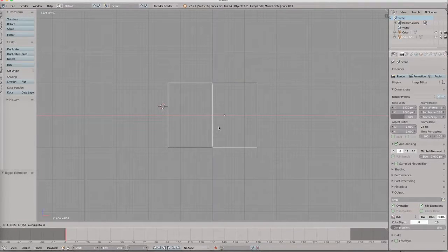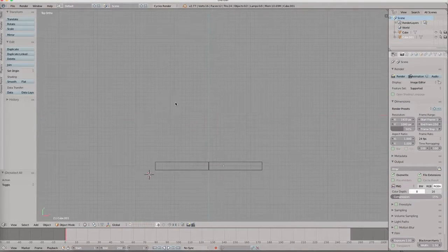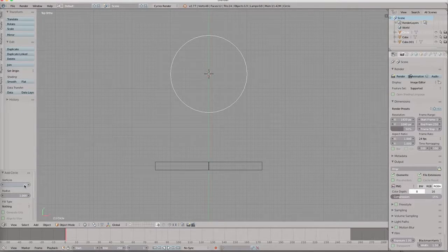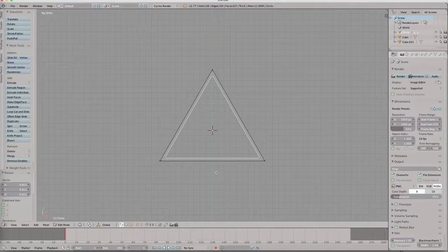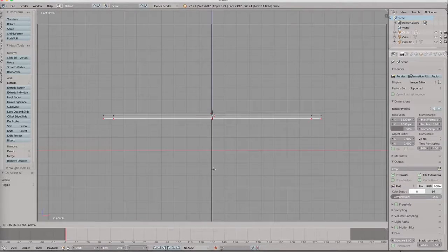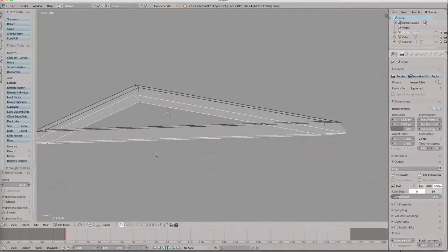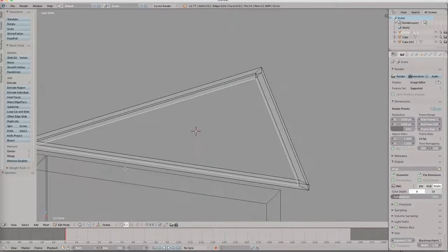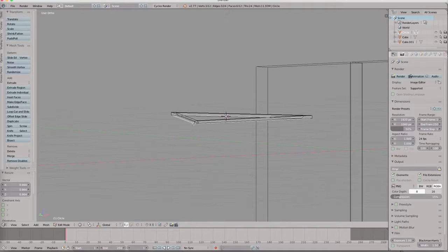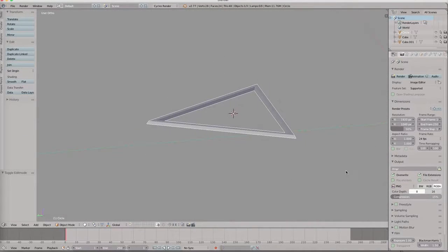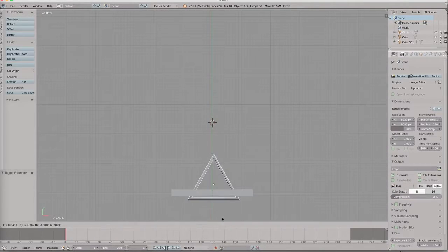When I'm doing non-organic objects that are more robotic or more like a door or something that's a machine, I like to constrict my axes to the X, Y, and Z when I'm extruding and beveling. So just a personal note, that's a good practice. I found if you start to try and extrude things when you're in perspective mode, sometimes you'll go askew with your geometry.